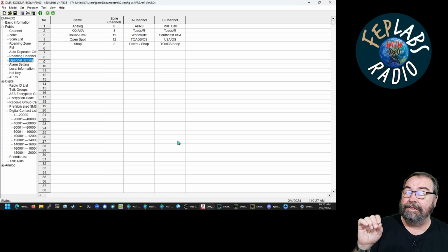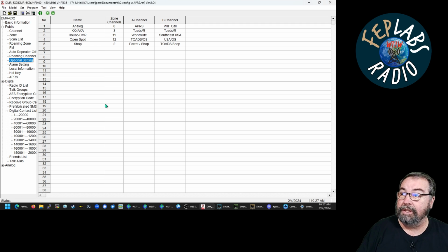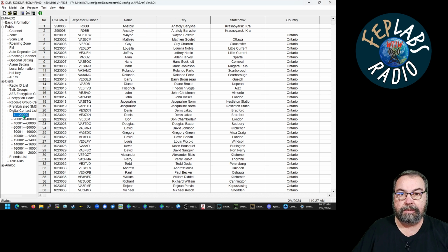Nine times out of 10, you don't need to fool with any of that stuff. If you follow these steps, you will have a working DMR radio. The last piece to the setup before we move on is the digital contact list, and that's what it's called in this CPS here. You can download all or part of the DMR database to your radio.